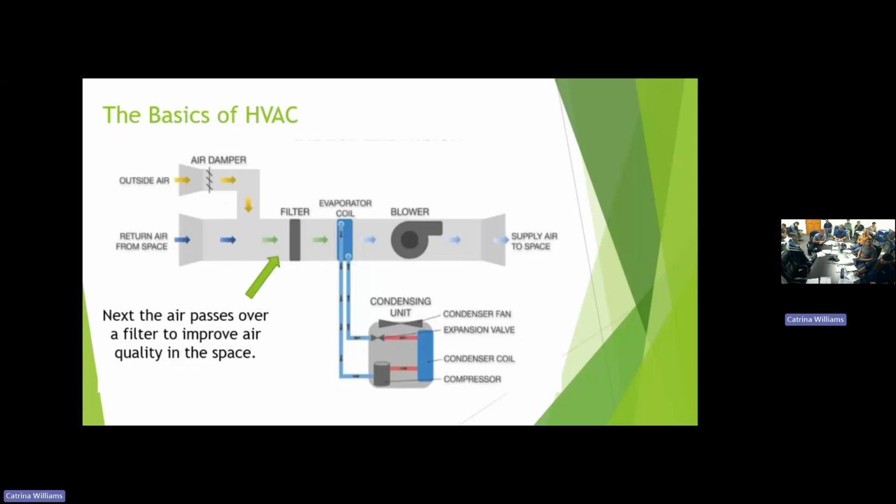Once we get past that, then we're gonna put it over a filtration system. And this is all based on the application. In this building here, you might get away with a MERV 7, MERV 10 maybe. You go into, say, a hospital, the MERV rating has to be much higher in that application because of what they're doing. But we can then filter the air and air coil in, which we're going to get into next.